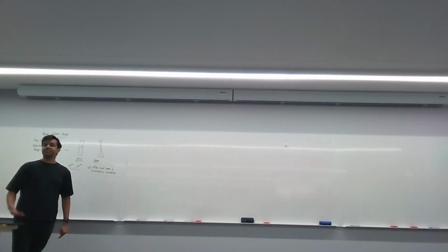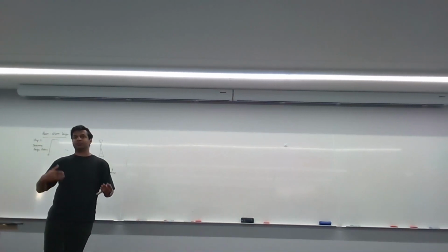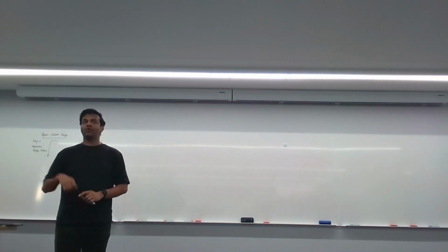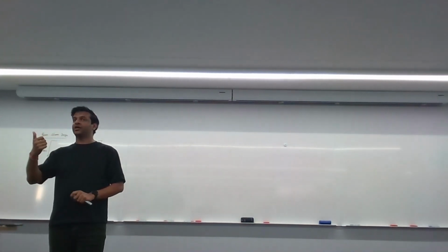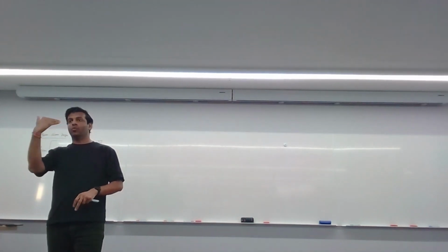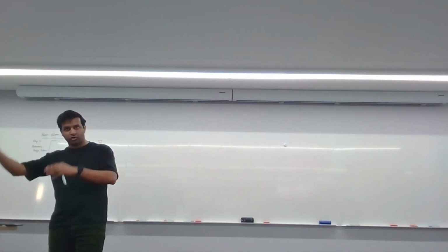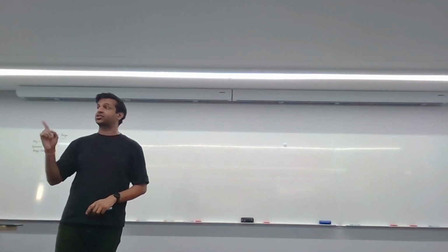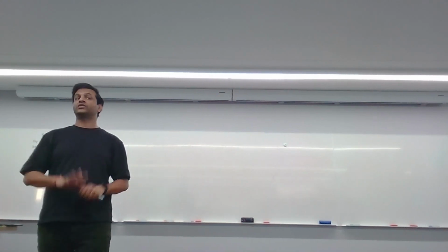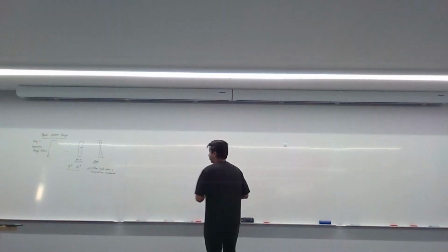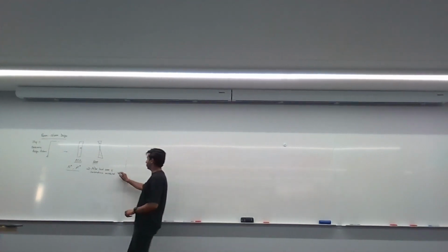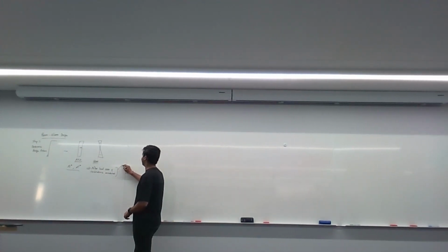So what load combination would you be using if there's wind involved? There are two types of load combinations if there's wind. One load combination is your 1.2G, and then you've got Q in there as well, and then you've got wind. The other load combination is for wind action reversal. What does that mean? The reason there are two wind combinations in the code in AS 1170, by the way, your load cases and load combinations are from AS 1170.